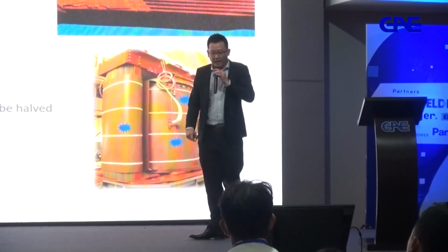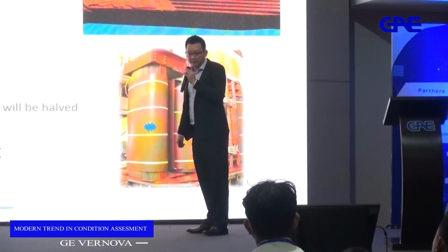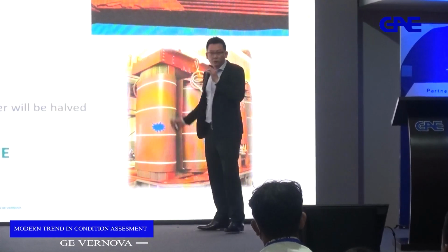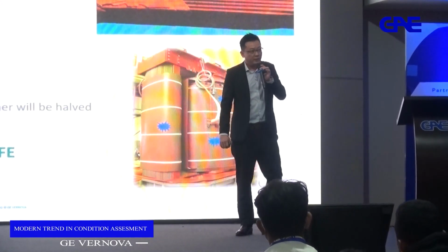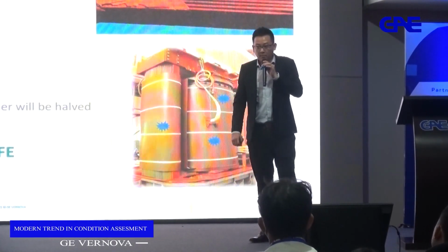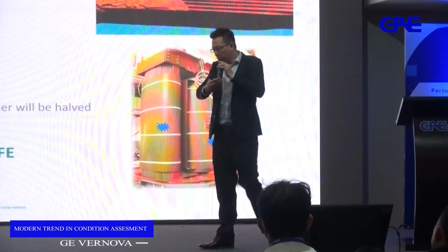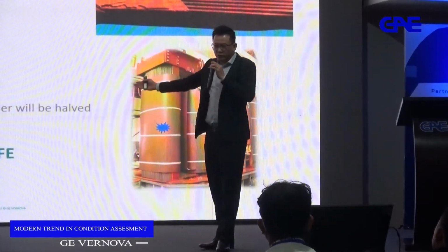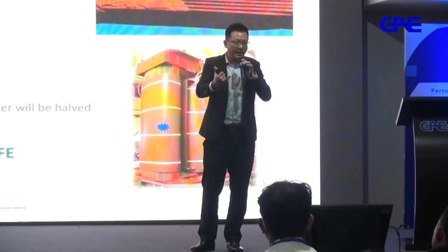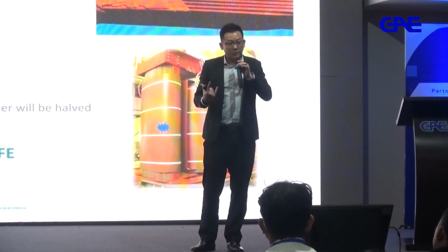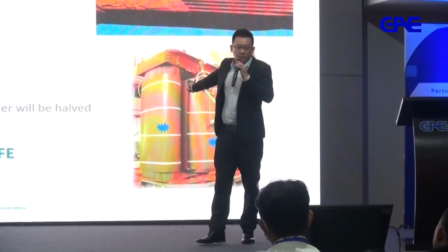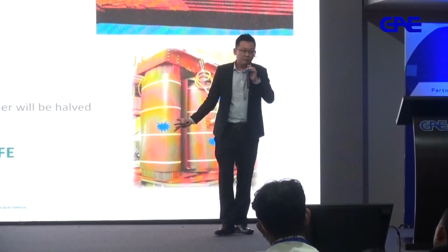Take for example, I have 30 ppm of moisture inside oil. The transformer life could be, let's consider, 50 years. But in a span of probably 2 or 3 months, the moisture rises to 60 ppm, which is double. So 50 years of transformer becomes 25 years.